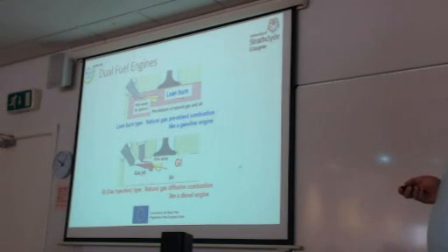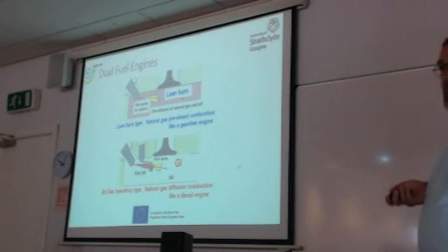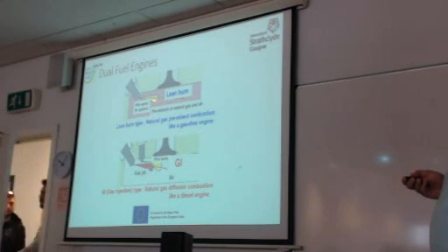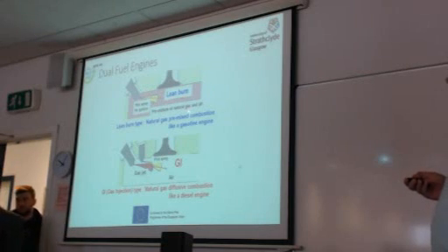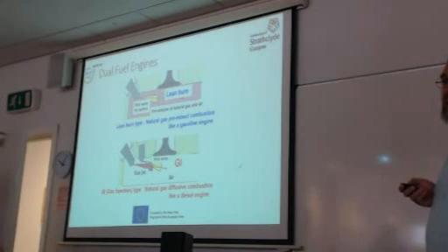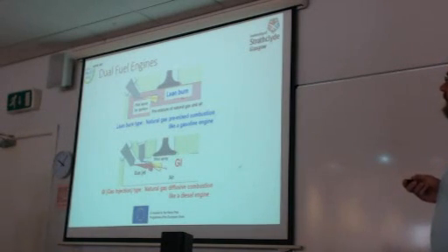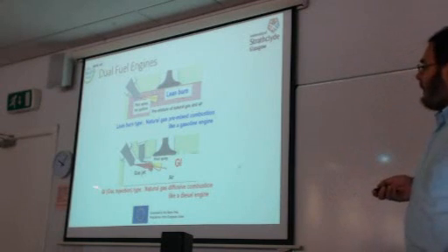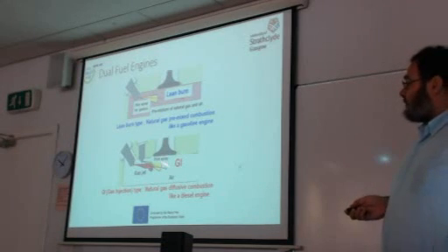So we have, as I said, the lean burn or premixed combustion. In this case, in the combustion chamber and close to the end of the compression process, we have a mixture of natural gas and air. The pilot fuel is injected there, and we have a jet developed within the combustion chamber. And then when the conditions are appropriate, the combustion will be initiated, and that will provide the initiation for the combustion of the gas air mixture contained in the combustion chamber. So this is the lean burn combustion or premixed combustion.